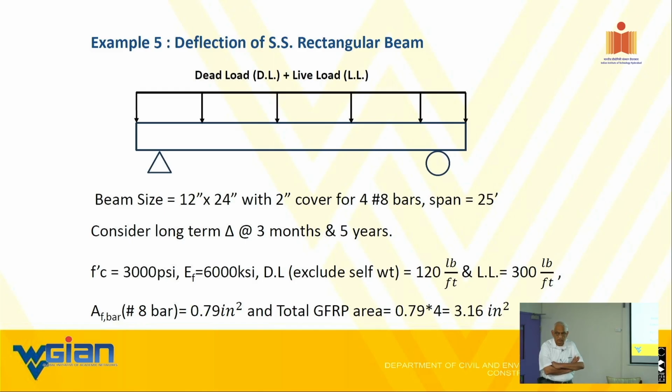So it is an inverse curve, it goes up. About 60% of total creep deflection takes place within about 6 months. 80% takes place within 1 year. After, of course, there is going to be creep after 5 years, but maybe 1 or 2%, but it's negligible. That is the word.